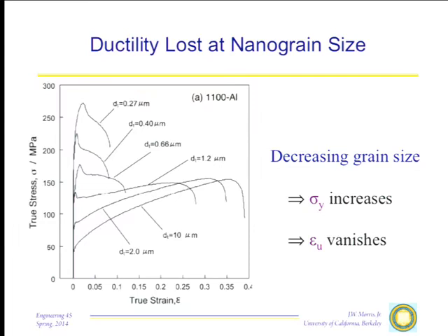And as I mentioned, in many structural applications, part of the specification on the structural material will be the yield ratio, which is essentially the ratio of the yield strength to the ultimate tensile strength. And they will require that to be below a certain number, which guarantees them a reasonable regime of plastic deformation. That's a safety factor. If you inadvertently exceed the yield strength, you want to have enough hardening in the material that the result of exceeding the yield strength will be minor deformation of the material rather than fracture.